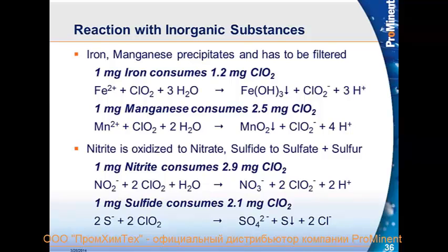One thing you do have to be aware of when sizing a chlorine dioxide unit is that it does react with iron and manganese, as well as some nitrates and sulfides, but the two main culprits here are iron and manganese. So before we size up a chlorine dioxide unit for any application, it could be a winery, it could be a hospital, it could be a rendering plant, it could be a number of different things in the applications that we use it for, we have to know the water analysis to make sure that there's not too much iron or manganese that's going to consume chlorine dioxide.